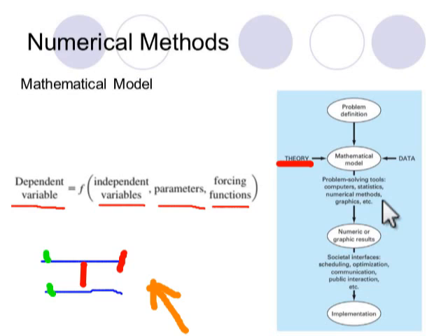For example, you make a simulation and determine the stress distribution in a bracket, and you share it with the designer and tell the designer that there is a point where the stress is much higher than the strength of the material, so modify your design.